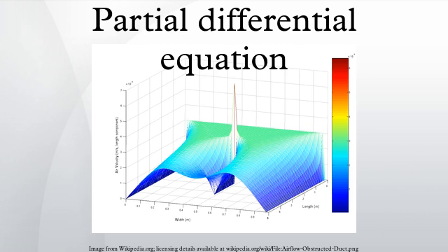Finite difference method. Finite difference methods are numerical methods for approximating the solutions to differential equations using finite difference equations to approximate derivatives. Finite volume method. Similar to the finite difference method or finite element method, values are calculated at discrete places on a mesh geometry. Finite volume refers to the small volume surrounding each node point on a mesh.